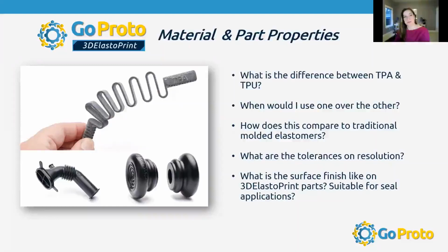Jesse, on a somewhat related topic, what's the minimum thickness of the parts? Yeah, great question. Like with most 3D printing, you're going to want to be aware of anything that's less than about 1 millimeter or 40 thousandths. And that is in individual feature size or wall thickness. We can build some incredibly thin parts like this part. I've got an orthotic shoe part that is about 1 millimeter thick, and it prints just fine. It also can be folded over and crunched, and it pops right back.